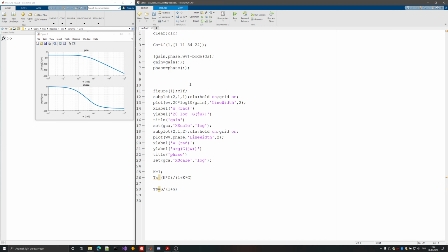Now, this approaching infinity is really important here. If you have a fraction that takes some values, for which case can we get infinity? Basically, 1 divided by 0 will tend to infinity. So we will check for stability by checking the denominator of this closed loop and whether it's equal to 0 or not. If we have a certain frequency for which our closed loop transfer function becomes 1 divided by 0, so if we get a zero division error, then we will have instability.